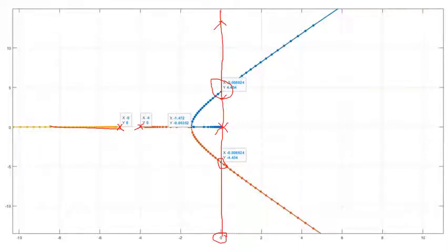Look at here, from -5 a new root locus will start and go in this direction, and there will be an intersection point. One root locus finally will turn in this direction, the other root locus will turn in this direction, and they will terminate somewhere at k equal to infinity. So when k goes to a very high value, these root loci will also terminate somewhere at infinity. That's the root locus plot for the given question. Similarly, in this direction also it will terminate somewhere at infinity. That's it for this question. We'll go for the next.